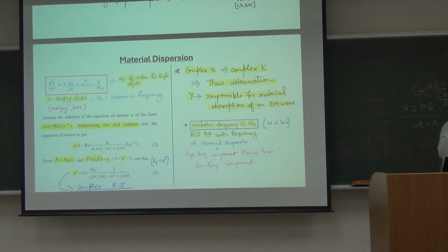So you have the omega beta diagram to determine the phase velocity. The phase velocity will be the slope of this line. This is going to give you the phase velocity. And then the slope of this is going to give you the group velocity.